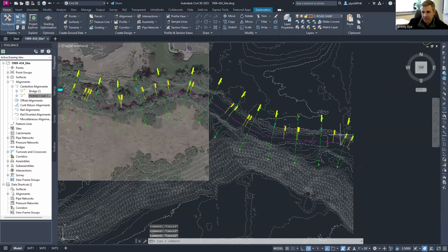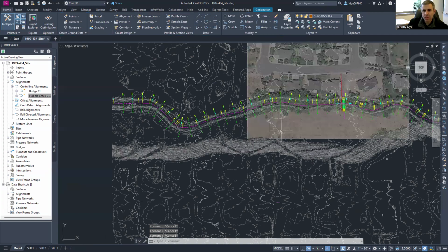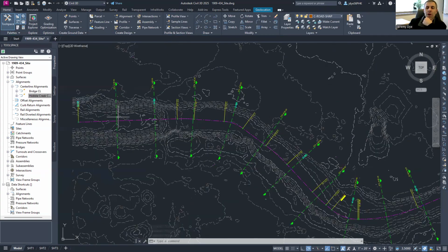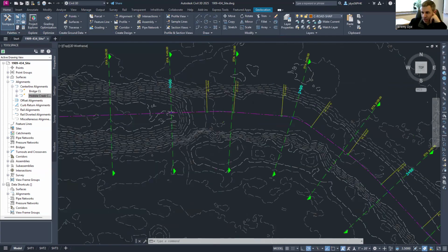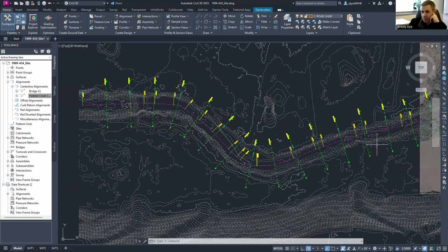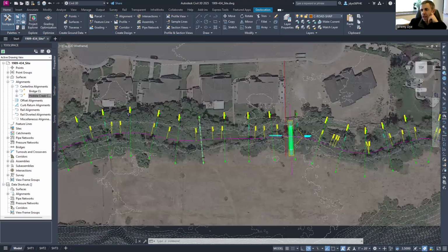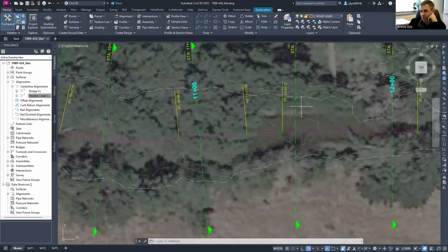Okay, once I have all my sample lines, next thing I'm going to do is identify where the river flow switches to the river bank. And the reason this is important is because in your hydraulic equations, you have what's called a Manning's n value that specifies basically the friction of the stream bank and the stream bottom on the water.